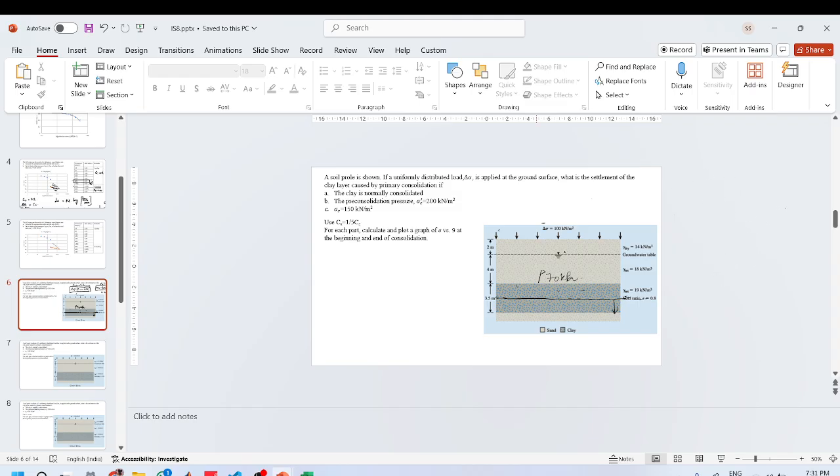So here it's already given that the soil is NC. That means that throughout the interval, see, we have been given delta sigma, we have not been given sigma, which does not mean that the soil has no pre-consolidation pressure just because we are starting from 0. There is a pre-consolidation pressure. If the soil has a pre-consolidation pressure of PC, it means that in absence of this load, the loading on the soil is PC.